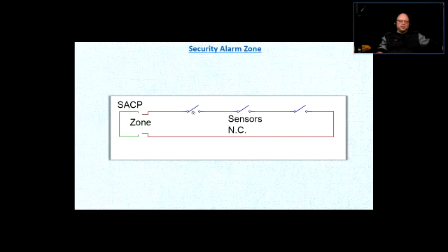open. Okay, so you can save the zones, because yes, you can put all the windows on separate zones, but you're going to run out of zones in the security system. So in order to save the zones, the amount of zones that will be available for you, usually the boards for the security alarms come in 8-zone capability. You can get expansion boards, or you can combine them in something that's called end-of-line resistors / the loop. So we talked about that last time. So this is how the zones are solved in the security alarm.